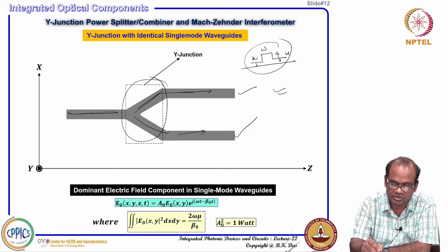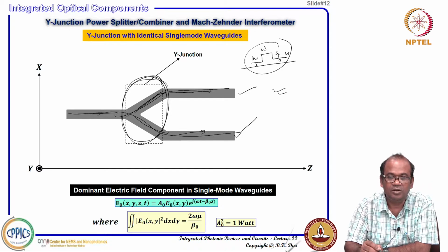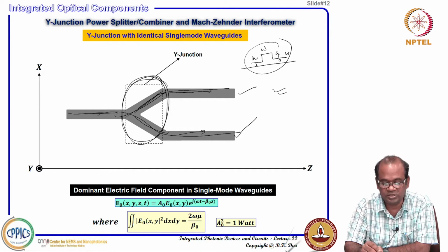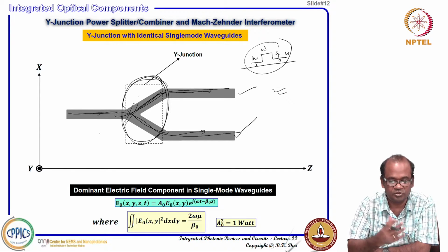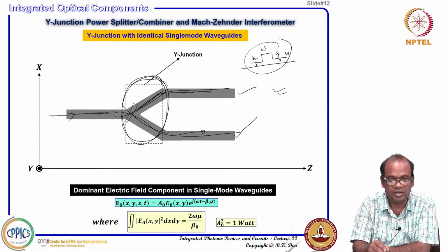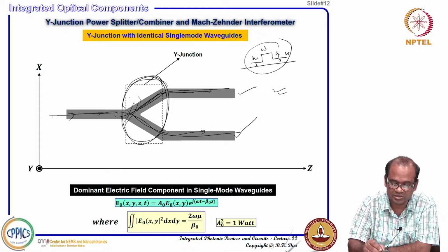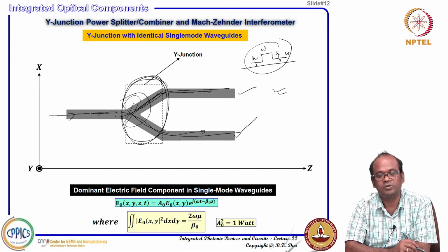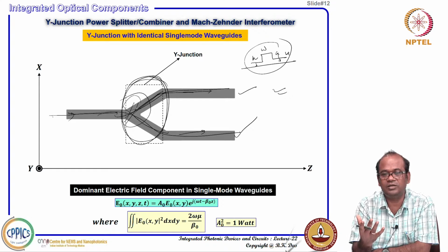This type of junction you can design such that you have almost no loss, but because of the junction there will be this type of perturbation, right? Your waveguide, whatever fundamental mode is propagating like an orthogonal mode, no power will be dissipated anywhere, it will keep carrying, but suddenly it sees some kind of abruption, some kind of perturbation. So there the orthogonality condition breaks.